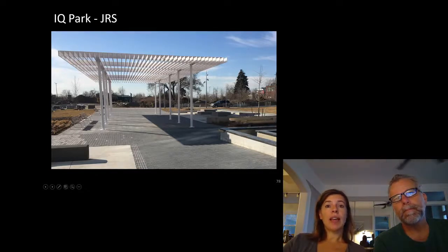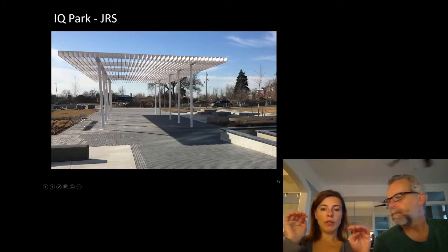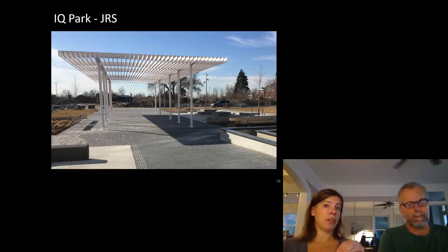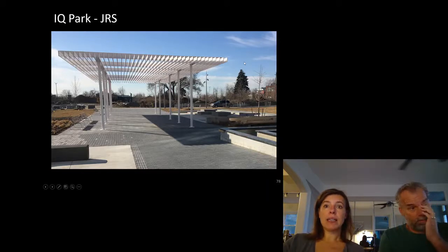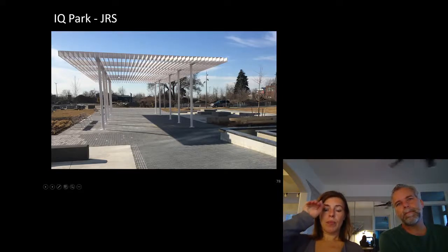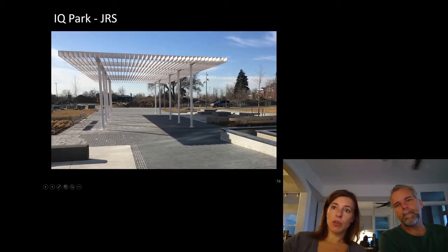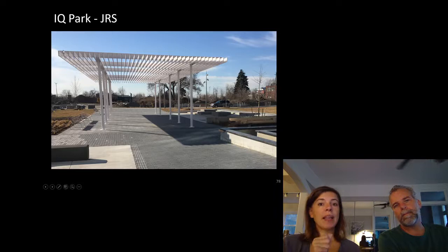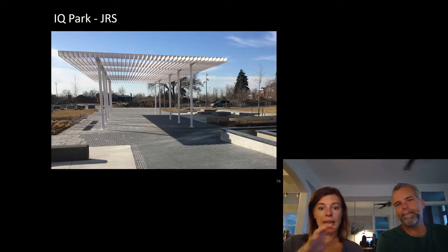I looked at projection and I looked at drag, and I compared the two, and depending on what direction it was, one used one and one used the other. For the top elements, I used projection in that direction and drag on these. And in that direction, I used projection on the front surface and drag along the rest of the surface. So this is where engineering judgment really came into play.